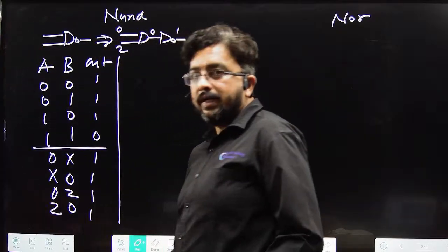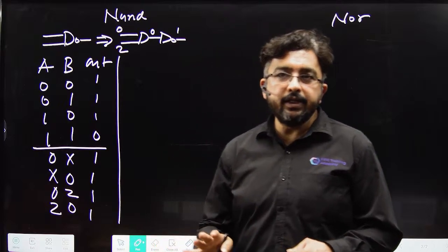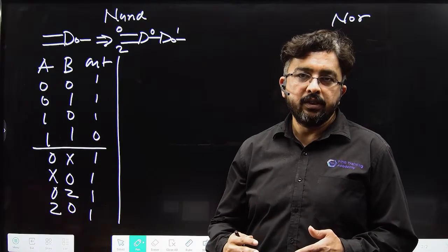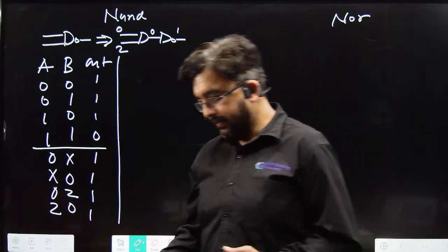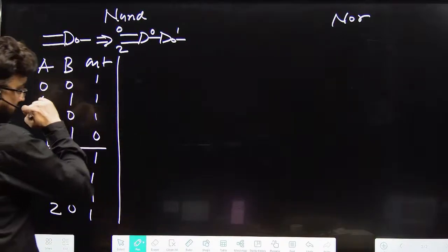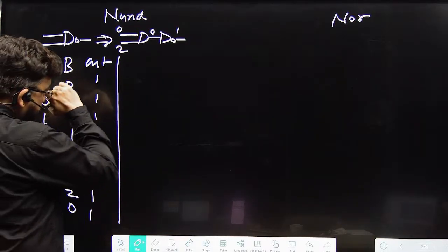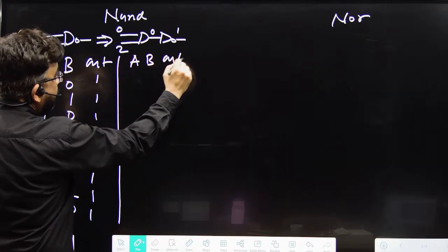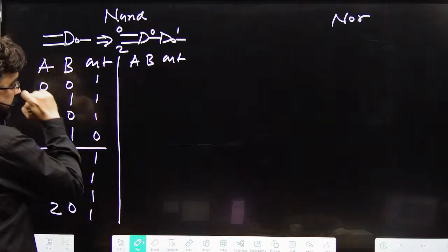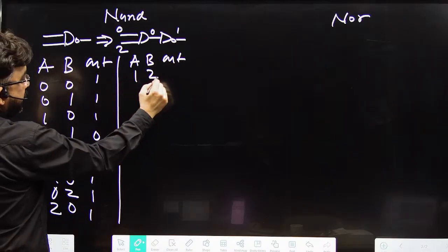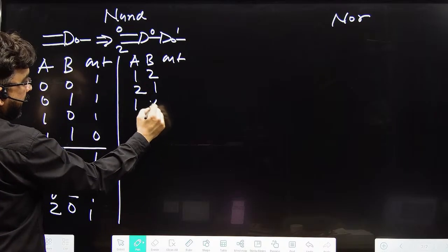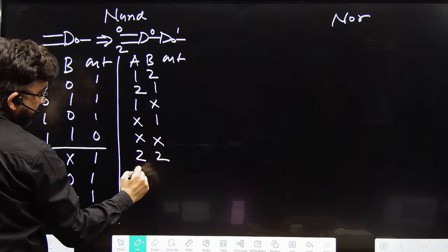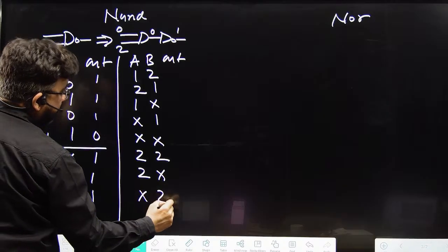when you don't have input 0. When you have an input 1 along with x or z, or x or z is the input, in the case of NAND, what will happen? I am talking about the NAND gate. So it is 1z, z1, 1x, x1, xx, zz, zx, and xz. Very important topic.